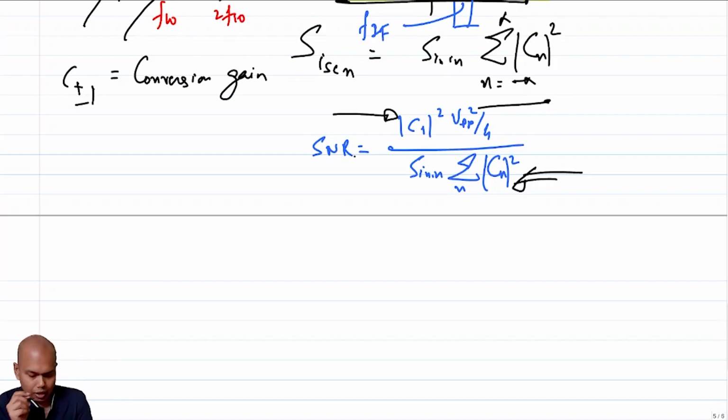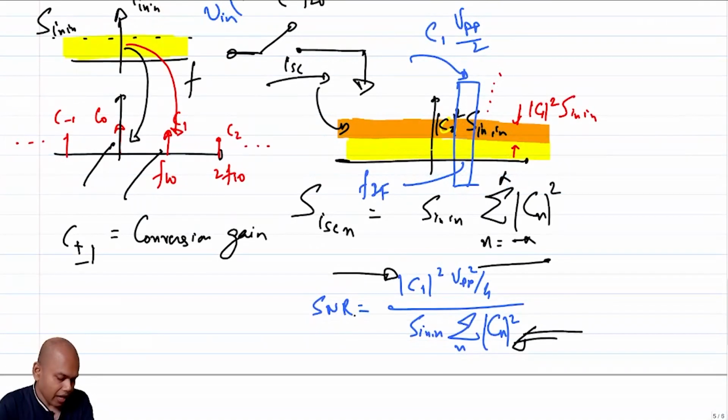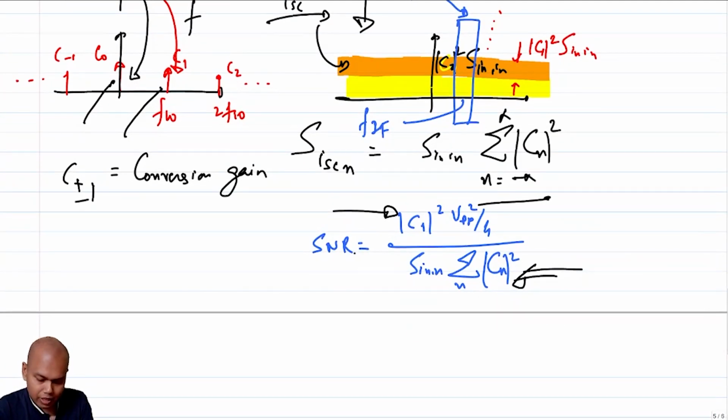Another piece of jargon is the bands that arise because of these C0, C1, C2 and all. These are called harmonic bands. These are often called side bands. There are certain side bands that you would want, and there are certain side bands that you will not want. But the key thing to note is that when you do your analysis of a mixer in a simulator, you will have to choose a sideband if you want to do your analysis.